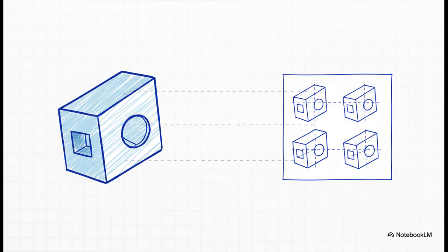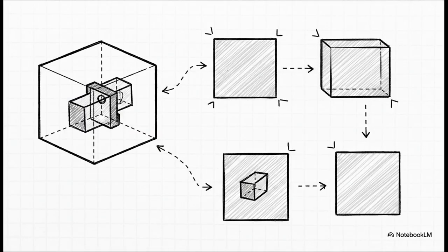And this is it. This is the big one. This is the core problem that every convention, every rule in technical drawing is designed to solve. How do you take a real-world object that has height, width, and depth and show it accurately on a flat piece of paper or a screen? The most common way to do it is with something called multi-view projection. Here's a way to think about it. Imagine you put an object inside a glass box. You look at it from the front and you trace what you see on the glass. Then you do the same from the top and then from the side. Now, if you unfold that glass box and lay it flat, you've got a perfect flat representation of the object from all the most important angles.